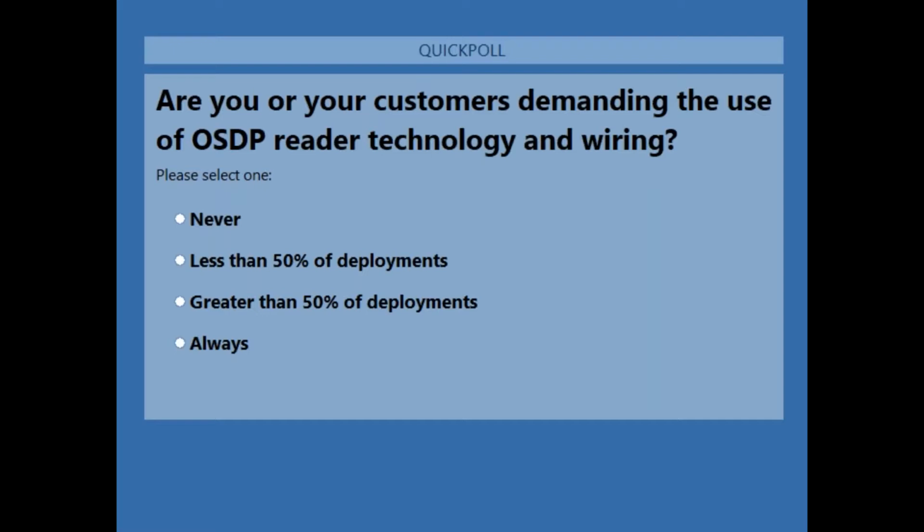Hey, Francisco, it's Jared. I did want to bring up that there is the option for addressing Avigilon MT series readers using a configuration card. If you need to get a hold of those cards, you will need to reach out to Avigilon directly. We don't have access to them in our price book, nor do we have the ability to get them. However, I have received a couple, and apparently they do work with the Avigilon readers, so you will be able to address 0 through 3 for Avigilon readers as well.